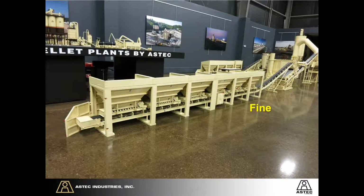As you look at these cold feed bins, they're always going to refer to the one that's closest to the shaker deck or the conveyors as your bin number 1. That's where you're going to put your fine material. And as you move through those bins, the coarser the aggregate will get. So you start out with very fine, and then it moves down and you become coarser as you get back towards the end of that. And as we go through the presentation, we'll talk about that and the reason for that a little more.